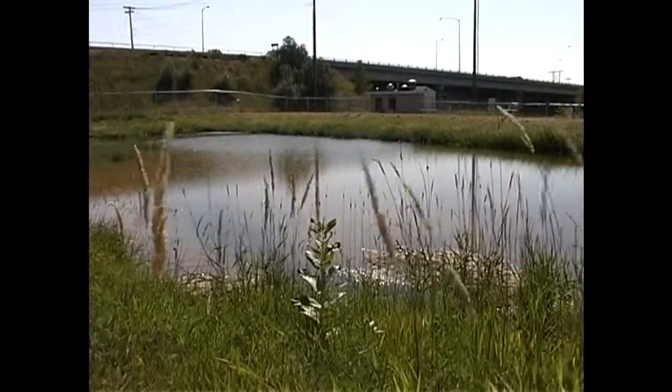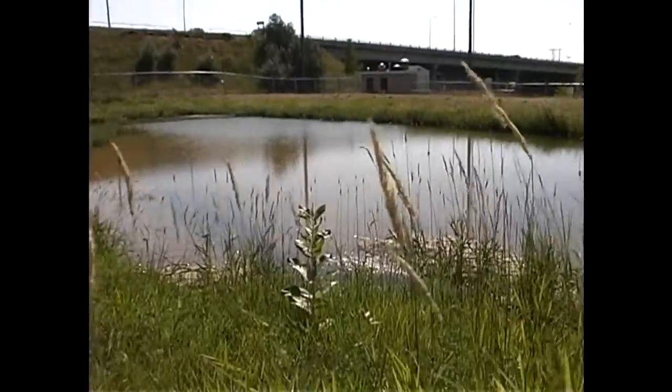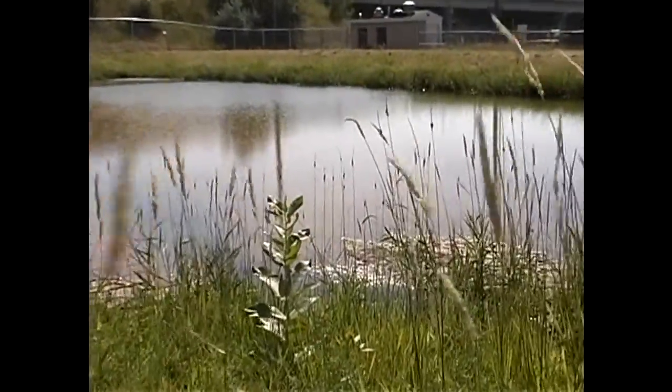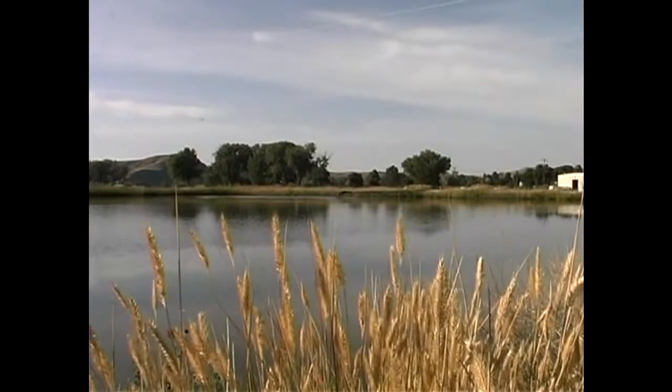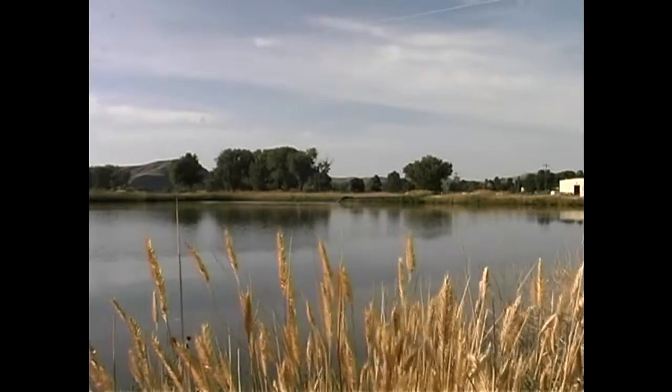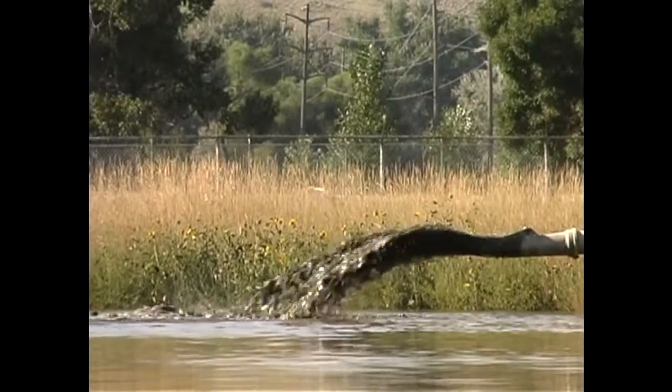Both the City of Billings and Lockwood Water District have tested the sludge. Neither demonstrated hazardous waste characteristics. We've tested for the arsenic levels. The sludge processes that we use, sending out to a sludge drying pond, have that tested for metals content, and it's showing that we can land apply that. So to this point, we haven't had a problem with land application instead of having to take it to a landfill. We have TCLP'd that sludge. The TCLP test to date has been non-detect on arsenic.